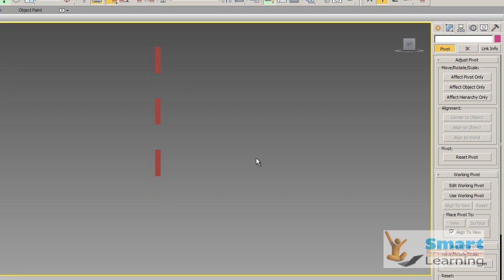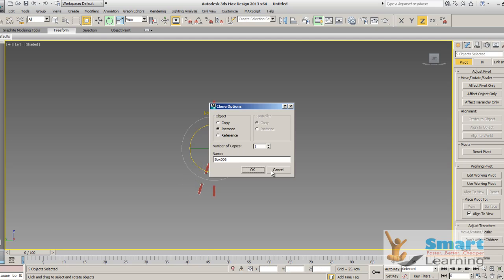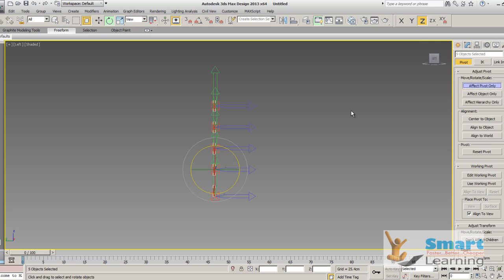Then I will just move it. I will switch off the snap. This is the point. So I will go to shift, and you can directly go to the rotate, and rotation handle you can set. So still the pivot point is not aligned properly. So I will go to the affect pivot, and whatever the pivot point you have, that for the rotations you have to align properly. Align to the object, align to the center. So affect pivot point I will going, and here is the center.